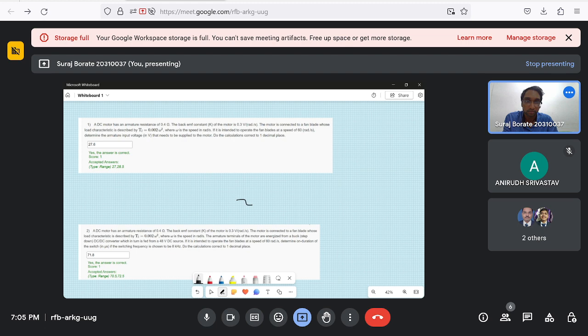Because this much was the change in the current in the time it was on, d into T. So now I can say delta I is equal to Vg minus Va times dT divided by L. Okay, let me check my notes.